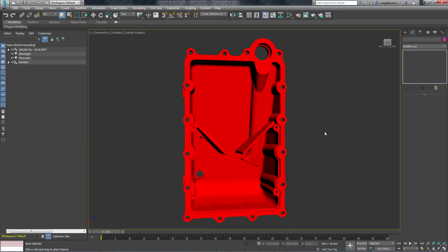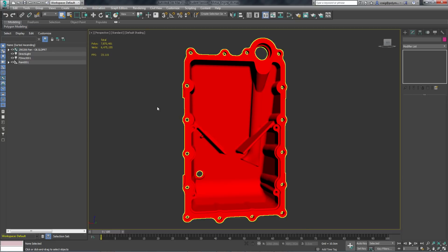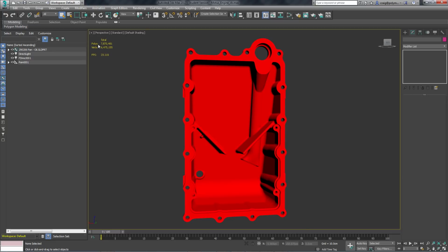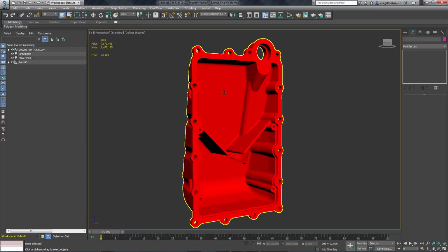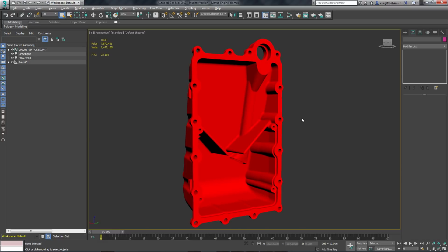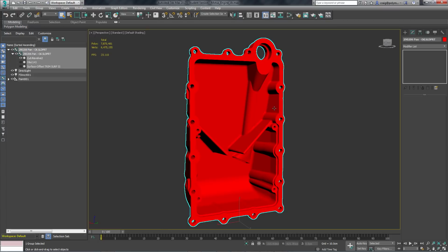Well, there are a couple good tools here in 3ds Max that we can work with. Just of note, when we're working with poly budgets and things like polygonal counts or vertex counts, in any viewport we can hit 7 in Max, and it's going to show you the overall poly budget. You can see that I've got quite a large number of polygons going on here with all these different parts and components of the engine and the overall bike in the scene. So for this particular piece, I want to decimate this down, or actually translate this into something that's a little easier to work with.